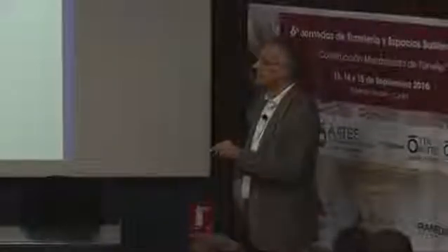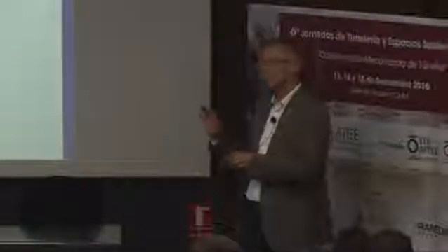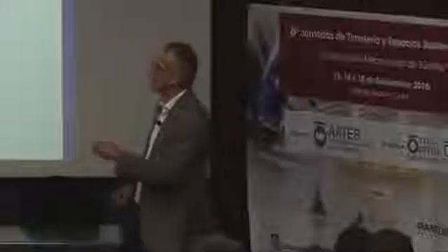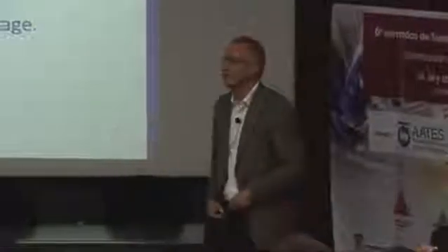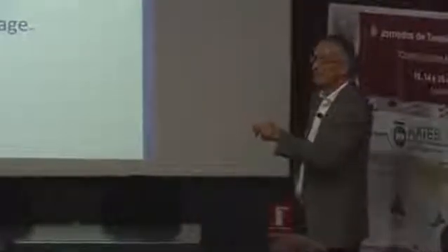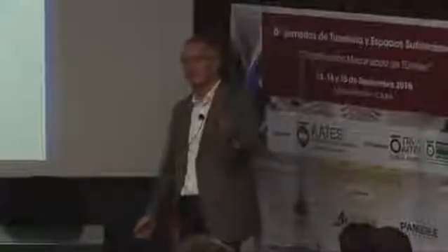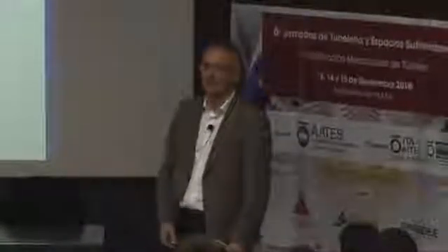So it's more sensitive to time dependency because the bentonite suspension in a loose ground area can, of course, penetrate a lot easier than it would have done into the in situ ground. So if you discuss too long why it happened, you have a secondary collapse, which might be even worse, because then it gets you inoperational. If a lot of volume comes in, you cannot turn the cutter head of the TBM anymore.